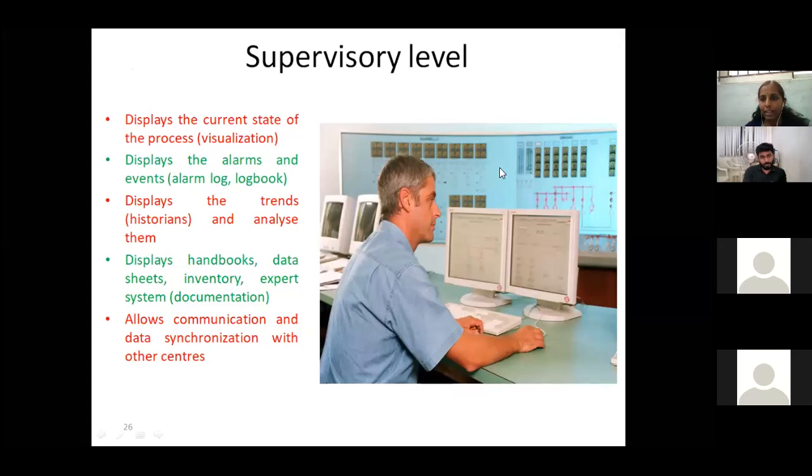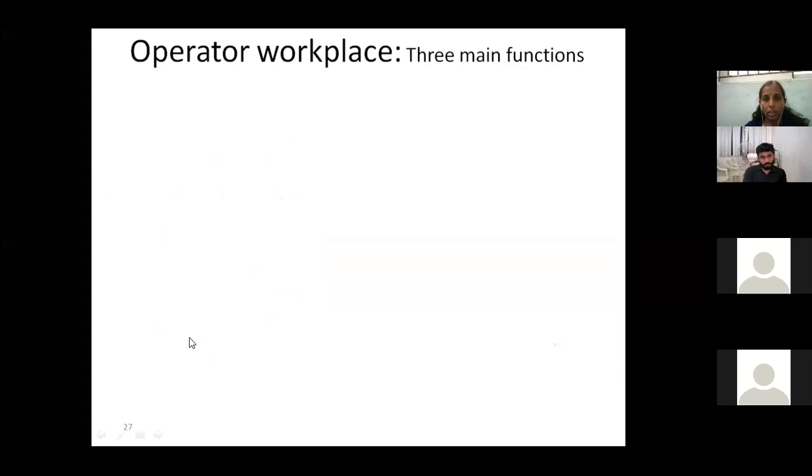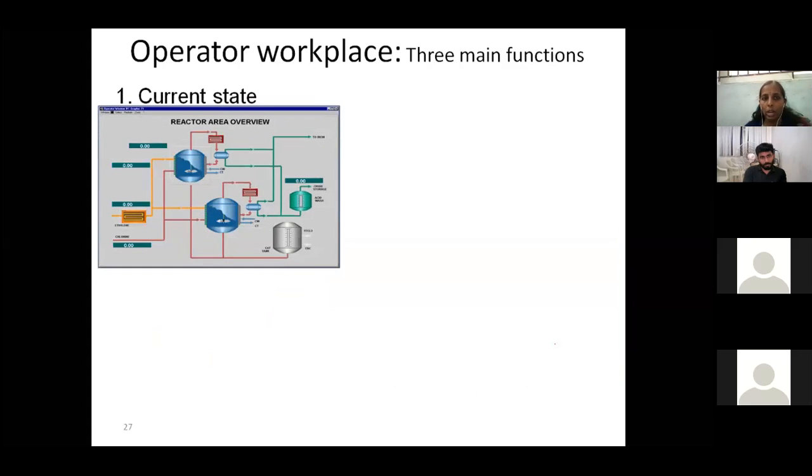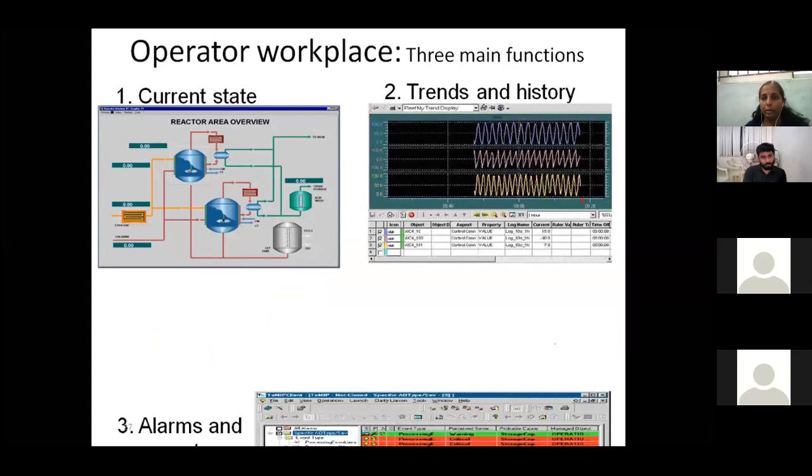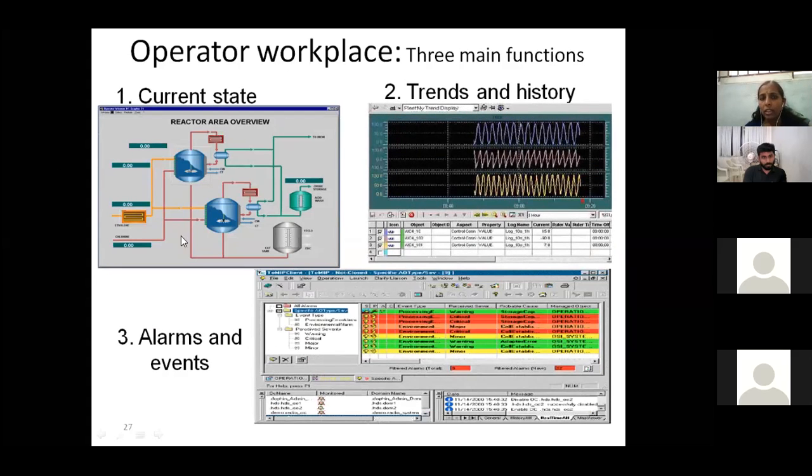So this HMI screen is used for performing all those functions. Let me show you how an operator interface looks. Here in the operator interface, for the entire plant, whatever realistic diagram I require, I can pick and place. You can right click on it and map the tag of your PLC programming. For example, assume that this is a stirrer motor.